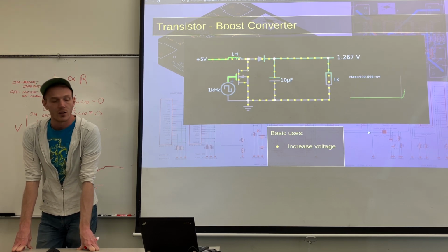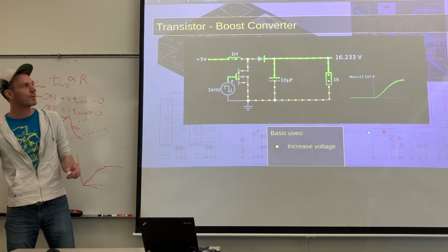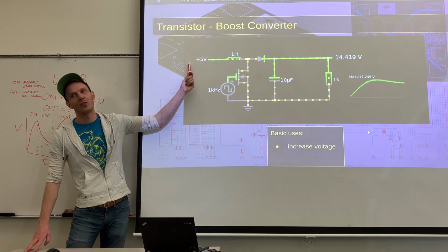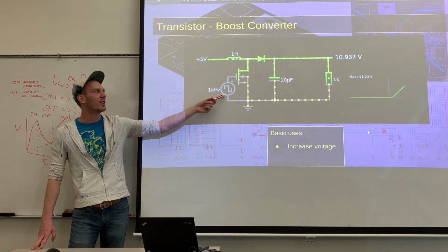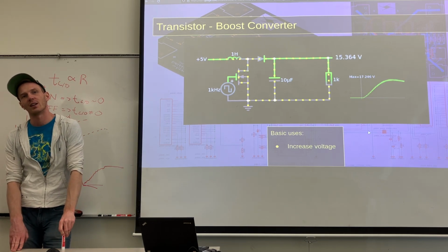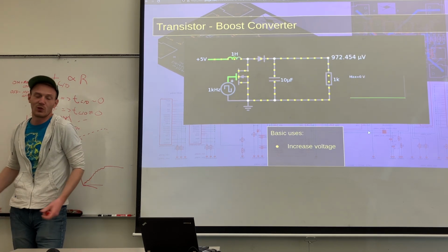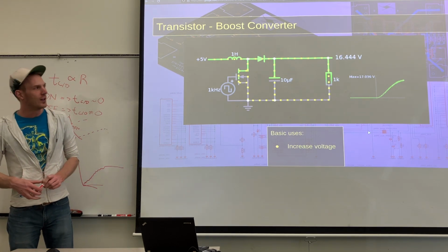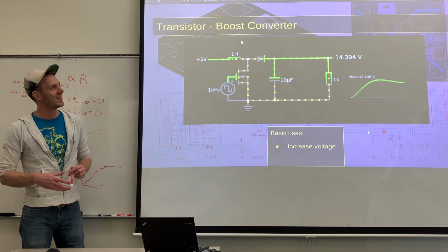The main reason that I did not start with these when we were making our own thing was that if we're coming off the battery for the first time, this voltage is also changing and things get really hard. Producing a stable 1 kilohertz sine wave can be difficult with variable voltage until you just say you want to buy a chip to do that. So doing that from individual components is a little bit beyond my enthusiast level of knowledge.